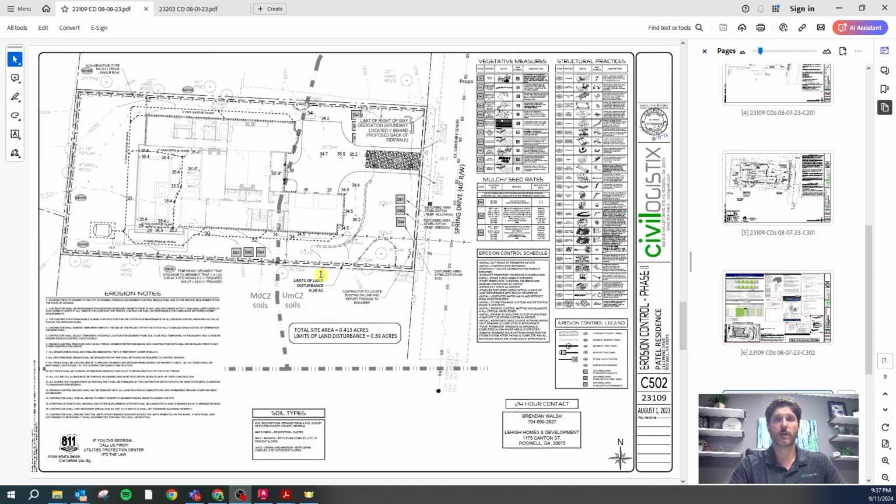So when we're doing a site that's less than 1 acre, we're going to just do that middle plan, which in our sheets is sheet layout or paper space C502. Probably in reality, we should have taken off this phase 2 and just called it erosion control. And there is no phase 1 in this plan, so there is no 501.